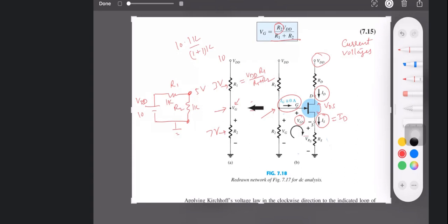The third thing is to take this loop; now you should know how to make a loop. This is IG, current flows from higher potential to lower. So this should be minus IG R2, but the value of IG is 0 in the circuitry, so this is nowhere in the equations actually. So we start from here: the voltage across it is 0, minus VG and plus VG you can do, minus to plus. If you go from this to this, minus to plus, plus VG, then VGS is from plus to minus, minus VGS, and this is IDRS, so minus IDRS equals 0.